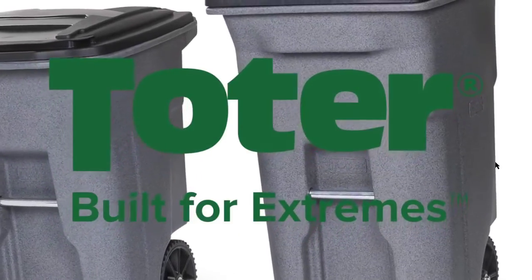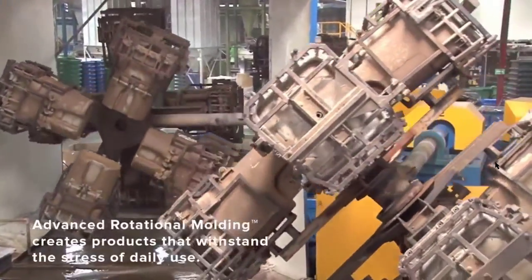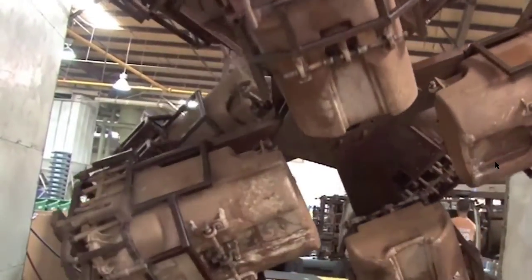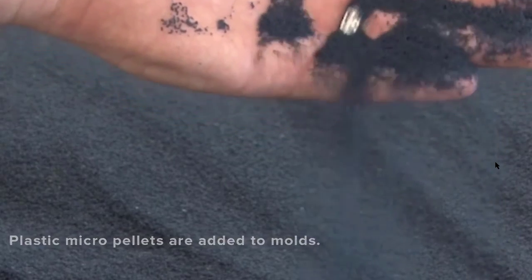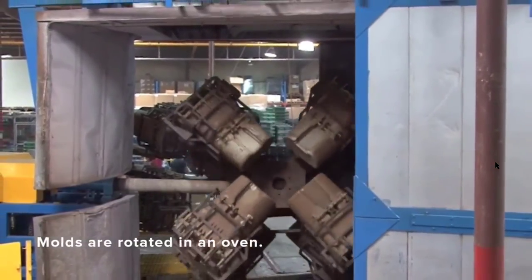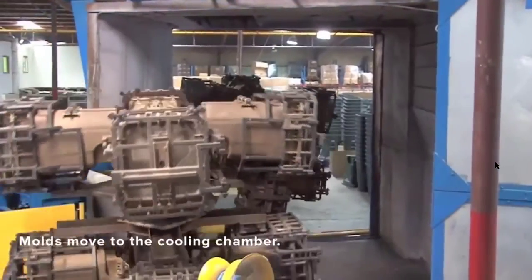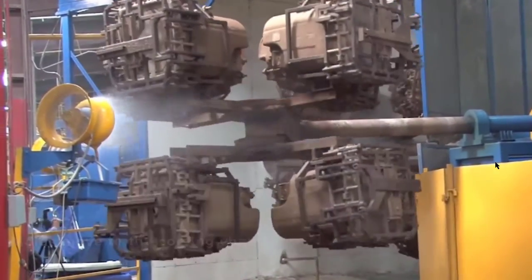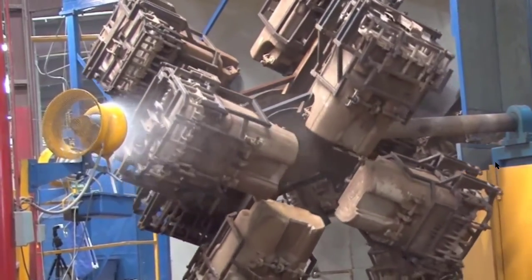Toter products are built for extremes. Our advanced rotational molding process creates products that withstand the stress of daily use. This unique process begins when plastic micropellets are added to molds. The molds are rotated biaxially in an oven until the resin melts and coats the inside of the molds. Next, the mold moves to the cooling chamber, where the temperature is carefully reduced with air and water to ensure optimal impact strength and performance of the final product.